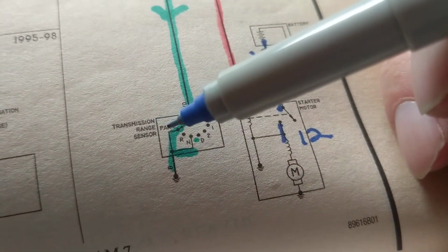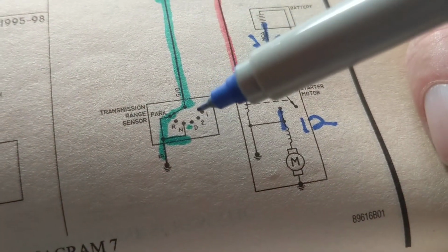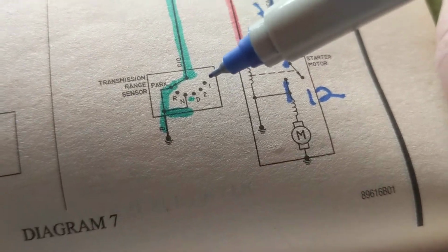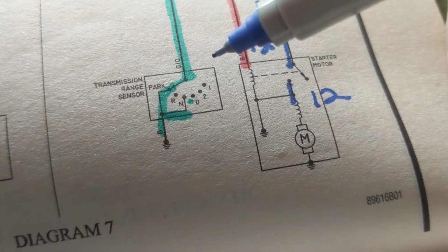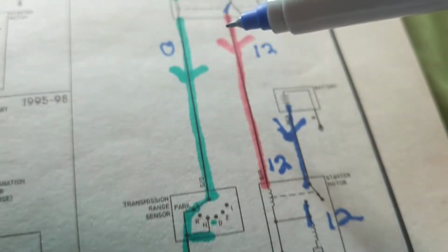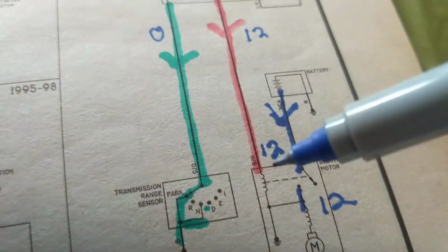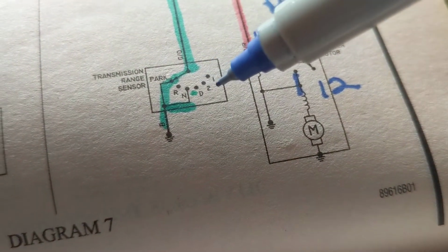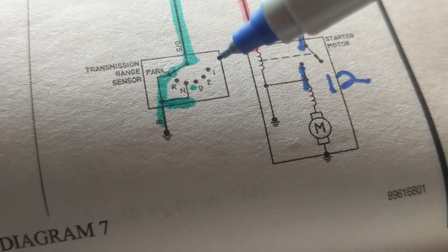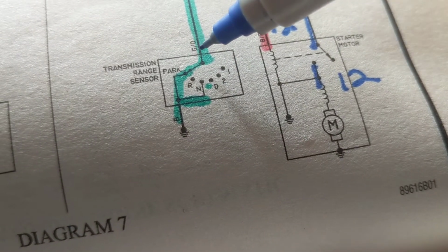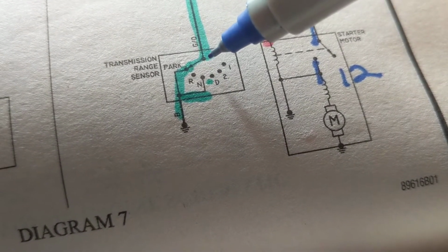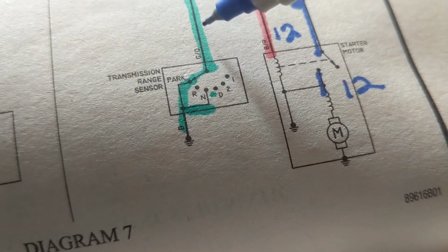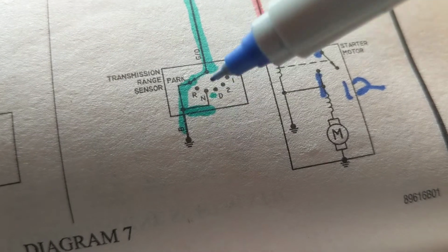As you can see, transmission range sensor. There's a connection that goes here. Now, we just saw the symbol. This is why I chose this schematic, because all the symbols that we covered are in this schematic. So we know the symbols, but we have to put everything together. This is a switch. We just said there are many selections in a switch. What will put this switch in a mode where the current can flow? Where is the complete path? As we say, we need a complete path for current to flow.